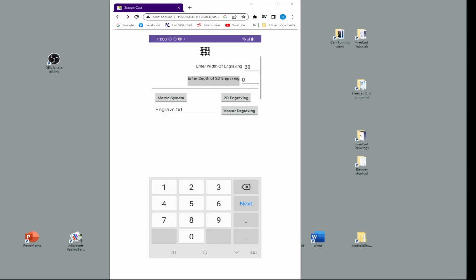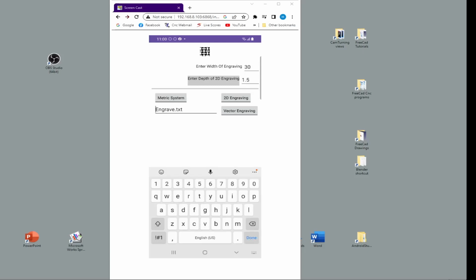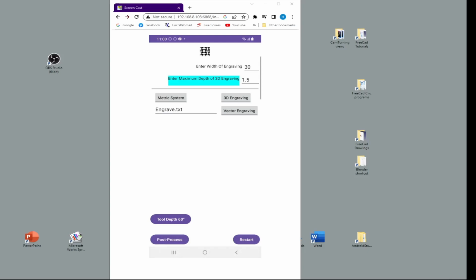I normally, on small jobs like these, use a 1mm ball nose cutter with a Z depth of about 1.5mm. I think there is hidden potential in 3D engraving of a grayscale image using ball nose cutters, especially in the wood router industry. I have created a few grayscale maps with RGB values between 0 and 255 and machine it like surface machining: vector engraving with your pixel size as a step over.